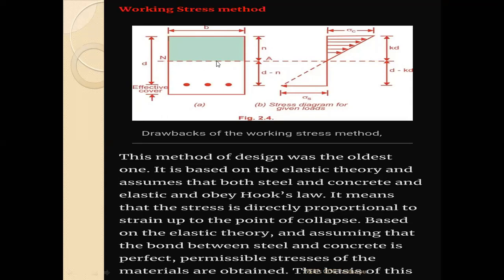Above this neutral axis, at any general distance y, if I take a strip, we will find that the stress is compressive in this zone. And below the neutral axis, where we provide the steel, the stress is tensile stress.